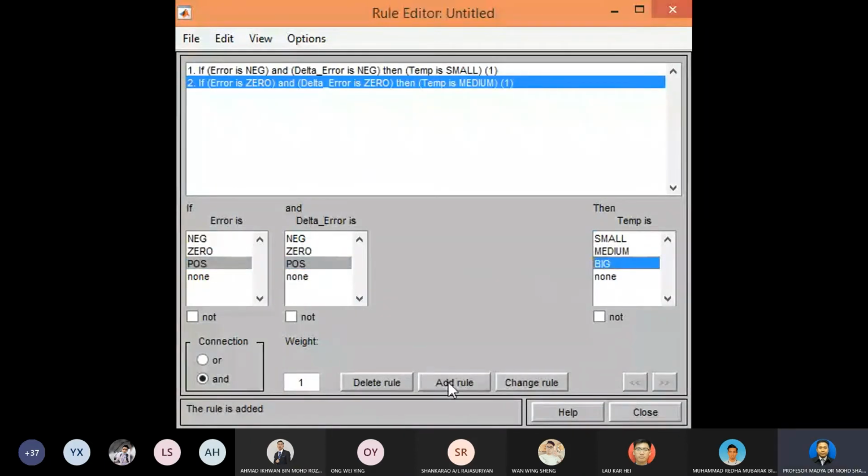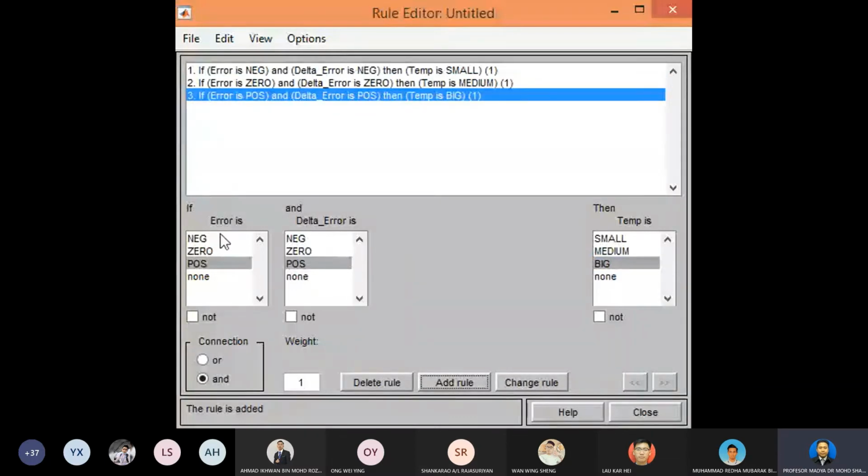For example, as I mentioned to you, if we have 3 for input 1 and 3 for input 2, that means we have 9 rules. This is some default, what we call the simplest method. Based on our input 1 and input 2, we know how many rules. But it's okay if you want more than 9 rules, for example, 50 rules.